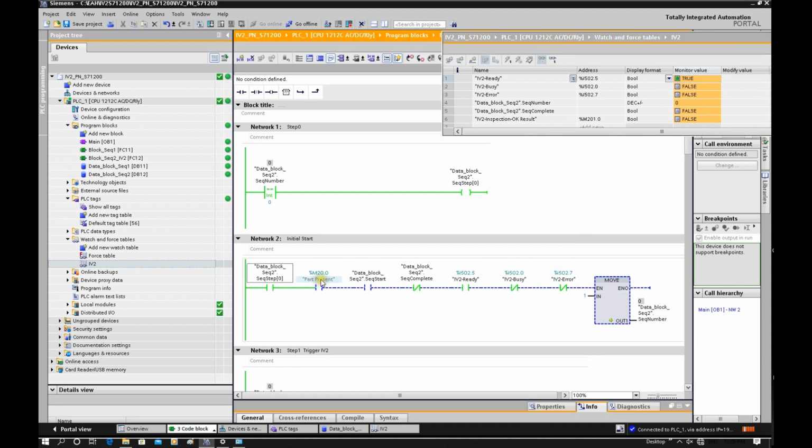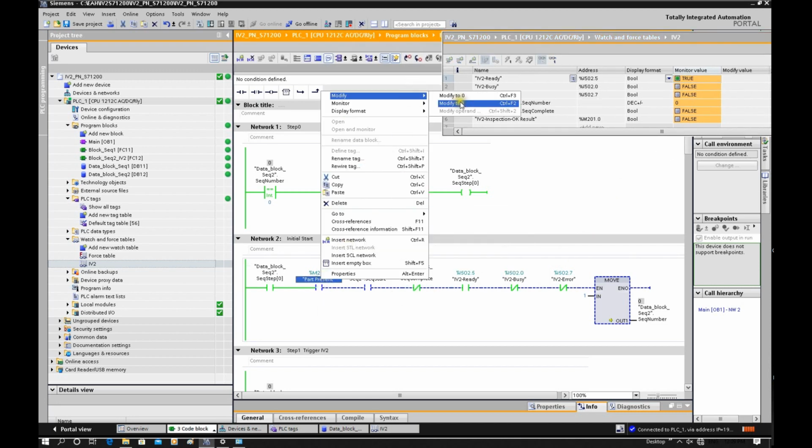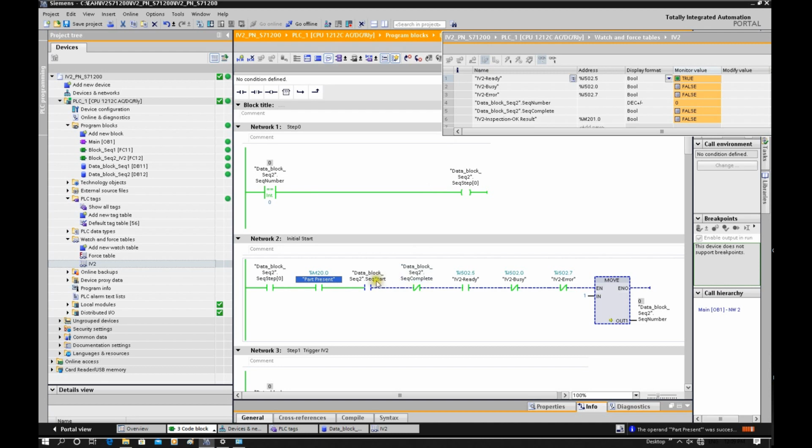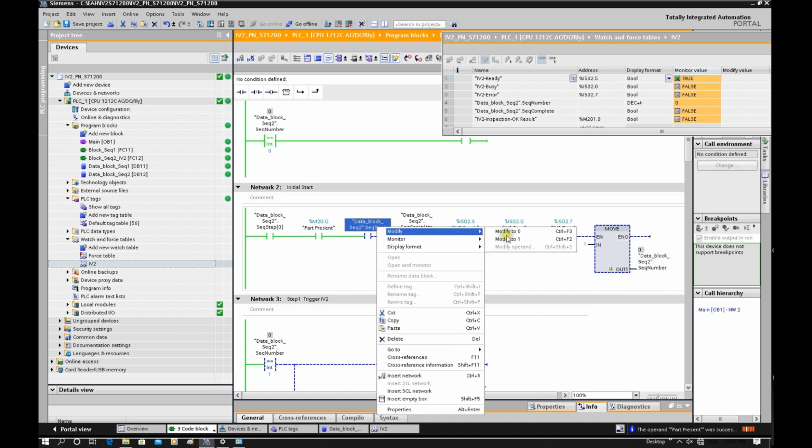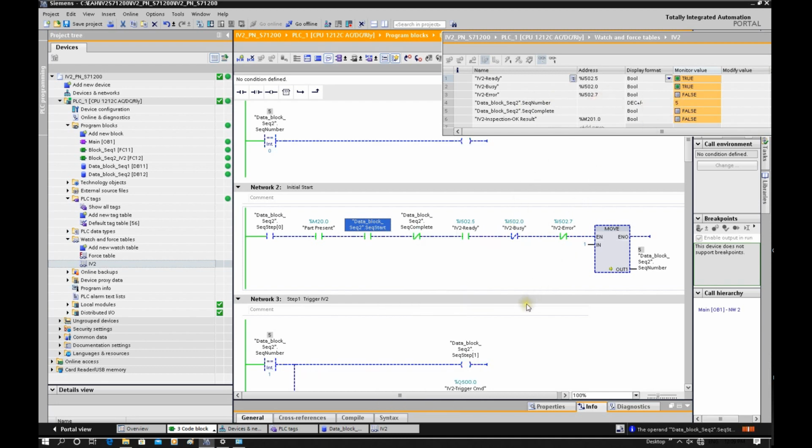So let's fire this part present. And let's fire this sequence start. This sequence will be very fast because the camera response is very fast. And keep in mind that with Profinet communication, the current cycle time is just 4 milliseconds. So this sequence will be very fast. Okay, let me turn it on. Meantime, you can watch this sequence number here. It will run very fast. So let's trigger. Boom. So now it's stuck at number 5.